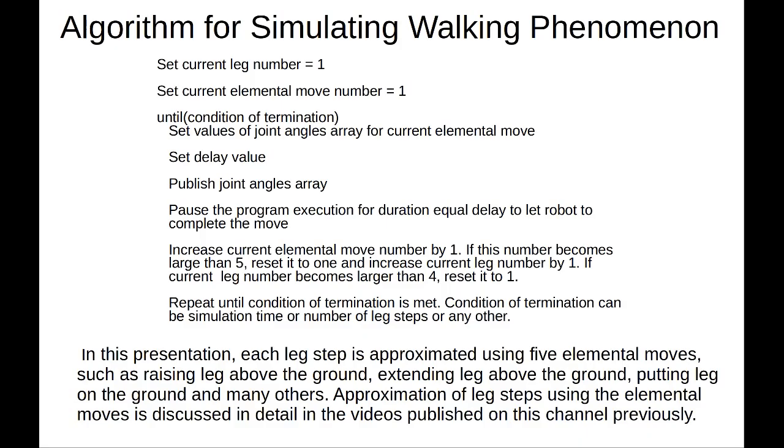Next, I will explain the algorithm for simulating the walking phenomenon. In this presentation, each leg step is approximated using 5 elemental moves, such as raising the leg above the ground, extending the leg above the ground, putting the leg on the ground, and many others. Approximation of leg steps using the elemental moves is discussed in detail in the videos published on this channel previously.